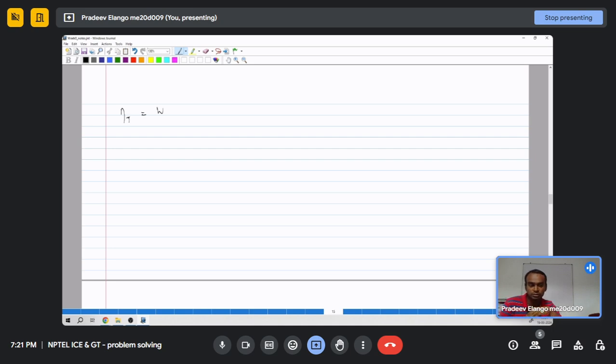So, I am asking only the isentropic efficiency of the turbine. So the ratio of actual work output of the turbine and the net input energy supplied in the form of fuel. No. This is isentropic efficiency of the turbine, that is actual work by ideal work output.